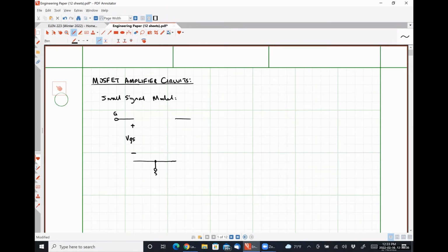And we are going to assume that the internal capacitances of our MOSFET are small enough such that they behave like open circuits at our frequency of interest, okay? So I know that that's kind of a weird thing because some capacitors we're treating as short circuits and other capacitors we're treating as open circuits, but it all has to do with the frequency dependent impedance of a capacitor. Okay, so we are absolutely going to update this with capacitance later, but for now, let's keep things simple.